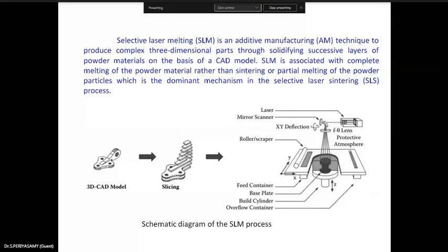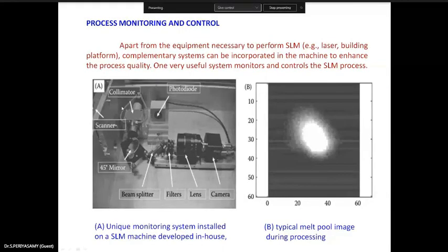The idea you can now derive using high-speed infrared thermography. This is normally used to obtain the imaging data for the prediction of microstructure. The microstructure will be taken from the particular part using a high-speed infrared camera, and the same thing will be used to determine the grain size. Once the microstructure images are taken, they will be interpreted in a standard method to find the grain size.